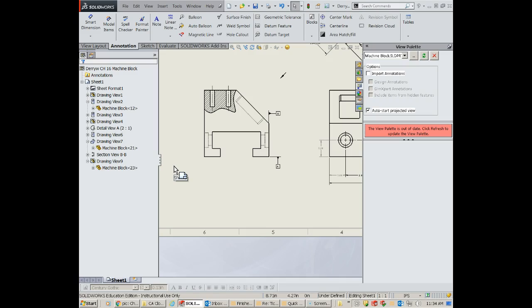Now on 17-8, there's a number of datum reference and geometric tolerancing examples. We're not going to be doing anything with our drawing with this. It's just referencing those, and we're not going to get into great detail on all of that. But depending on the part and the manufacturing tolerances, these are items that you need to start to become familiar with. We're going to add some hole specifications using the hole call out next.